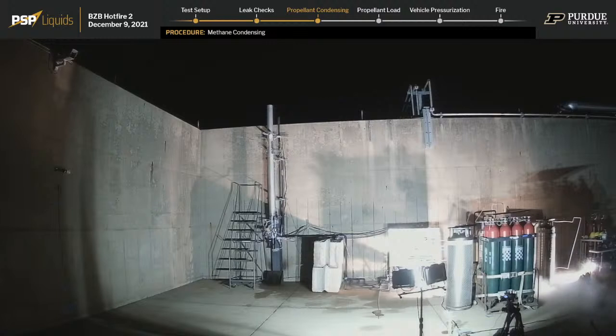But why do we swap a dewar? Can I have confirmation someone's wearing cryo PPE? Definitely is putting on the cryo PPE. Over. Copy all. We perform a dewar swap to make sure that we have adequate liquid nitrogen levels going into propellant load. This just makes us more confident in our ability to perform the test when we have a full load of liquid nitrogen available to the system before we do our hot fire. Right, and it's one of those great things about working at Zucro: we have a bulk supply of liquid nitrogen, so we're able to have this extra safety blanket that helps us.